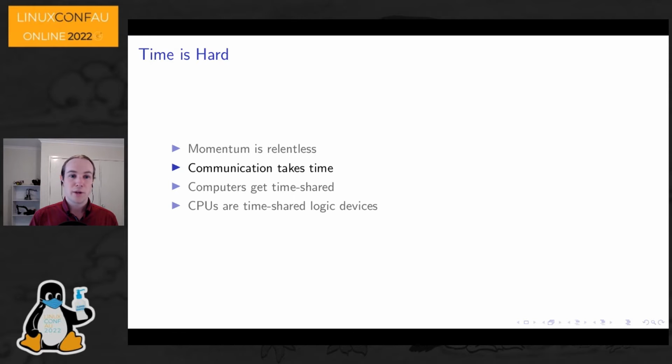The parallel port became obsolete and was replaced by USB adapters. The communication round trip of USB pushed the latency out to about a millisecond. The port throughput was the same, so consumer experiences were good, but motor commands would get buffered in the adapter, so an instruction to stop would get delayed behind instructions to advance. The additional buffering made the difference between an accurate measurement and a broken tool.